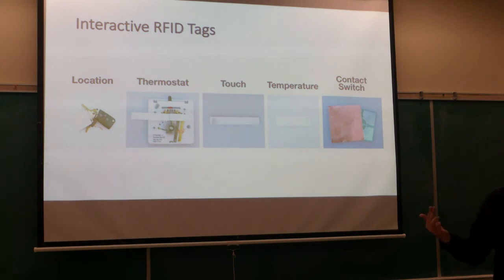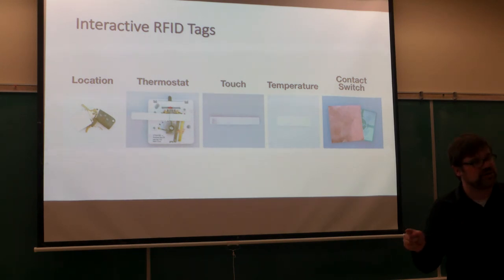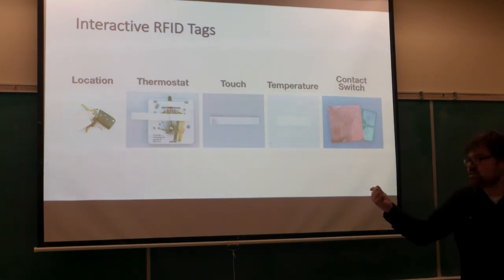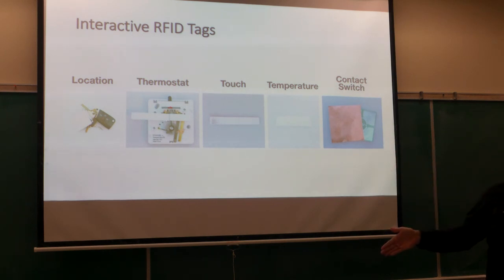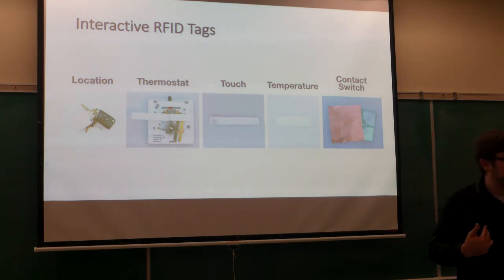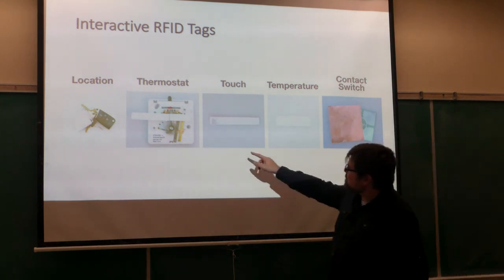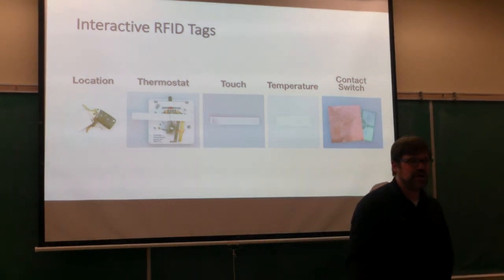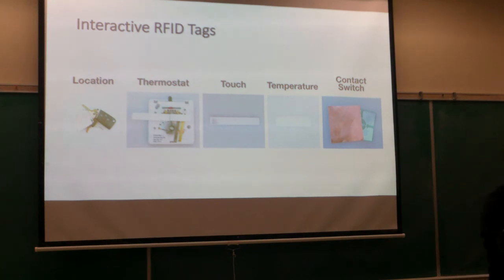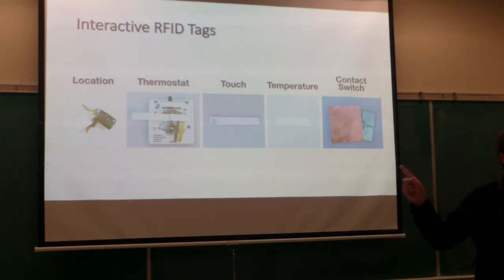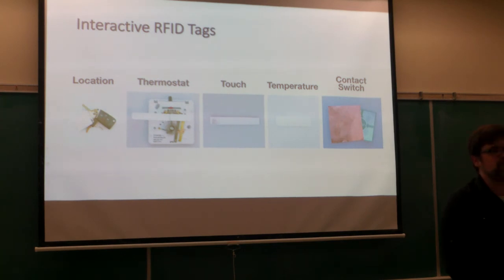Usually these components are tuned with the capacitor that's inside the tag. It turns out that the human body actually has a lot of capacitance. So we used one of these conductive ink pens to print a pad where you could put your finger. This is a tag that won't talk to a reader until you touch it. So you've created a touch sensor out of a normal tag.